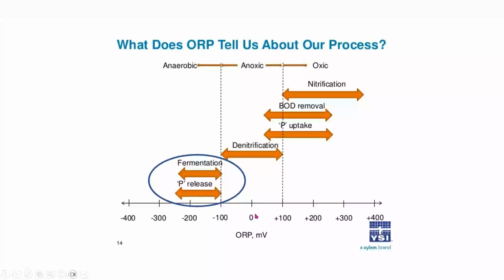So the DO stops at 0. With the dissolved oxygen, you can get down to about this 0 number, but you don't know how far over here you are. Then in the second environment, once we've energized them, we want the phosphorus uptake. That means pulling the soluble phosphorus out of the water column and the cells put it inside their bodies. That's the P uptake, the phosphorus uptake. And look at that. If you have aerobic enough conditions to remove ammonia, nitrification, you have aerobic conditions enough to remove phosphorus.